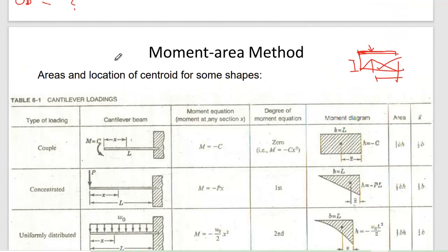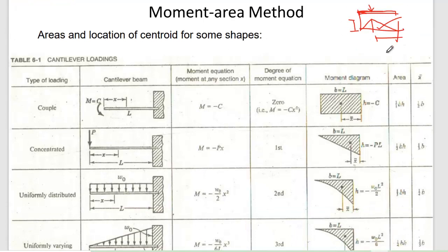The area of load can be used for the value of shear force diagram. The area of shear force diagram can be used for the drawing of moment diagram. So now, the area of moment diagram we are using in the calculation of deflection. To skip this kind of detailed explanation or calculations, we can use some shortcut here.